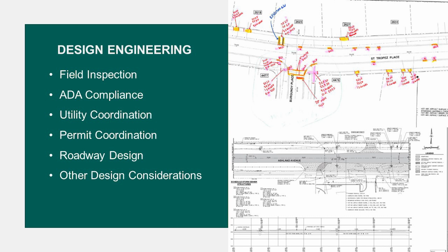We go and check for conditions of the pavement, areas where there might be potential patching that's needed. We also look for areas of curb and gutter removal and replacement, and also sidewalk removal and replacement. On sidewalks, we're looking for trip hazards. A lot of municipalities have their own criteria for how much they're willing to replace, what condition, how many cracks in the curb there are. Then there's also ADA compliance. I'll be speaking a little bit more about that.